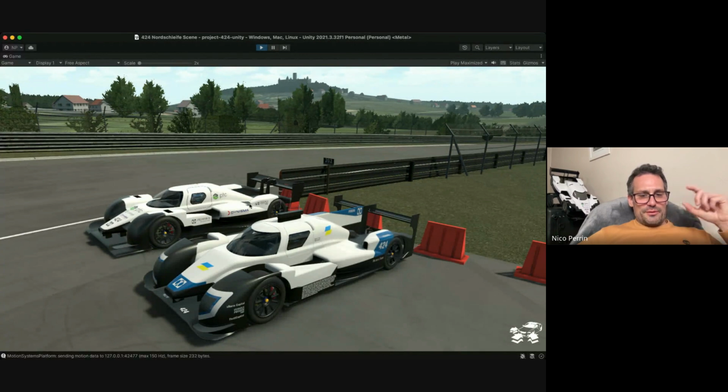Okay. Other changes, the rear brake cooling is higher at Le Mans. For the Nürburgring, we have less demand on the rear brakes because the lap is short and then we stop. For Le Mans, for very high ambient temperature, we need the ability for the race to open fully to have more rear brake cooling. At the Nürburgring, we'll set a record on a day where the ambient temperature is fairly low, so we can push the cooling down a bit.